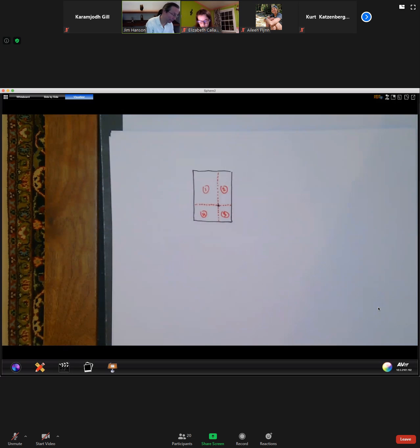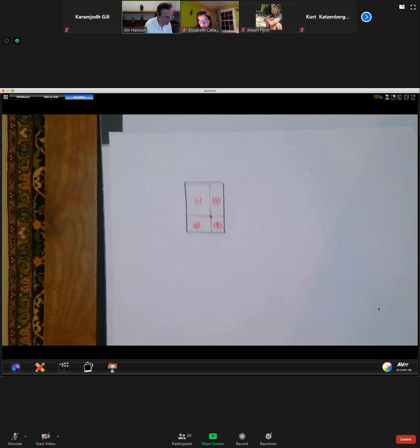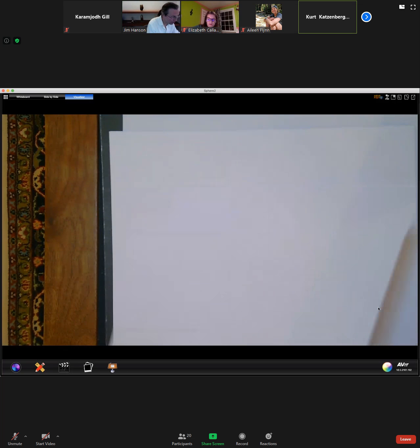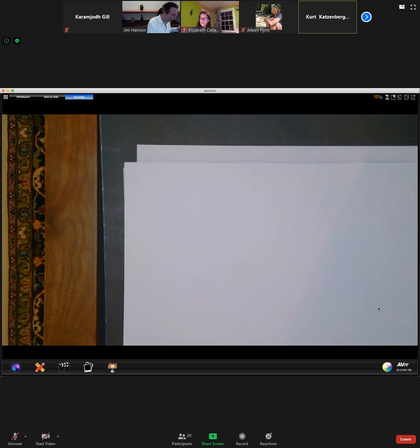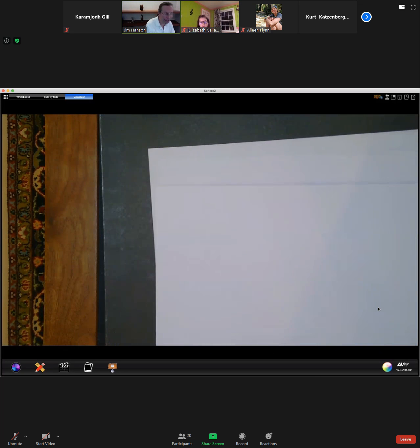So it's handy for rectangular foundations outright. You do not need to be at the corner. You need to be at the corner to be using it, but you can be clever and oversee that chart and actually use it beyond its intended means to some degree. And then we would just add all of the I's together, right? Like we did. That is correct. It'd be a summation of the I values, correct. Absolutely.